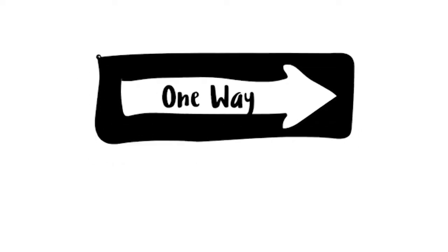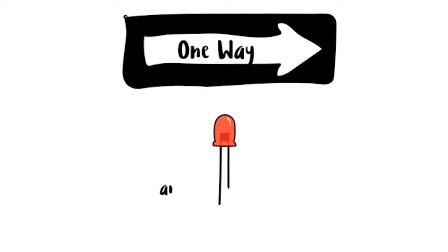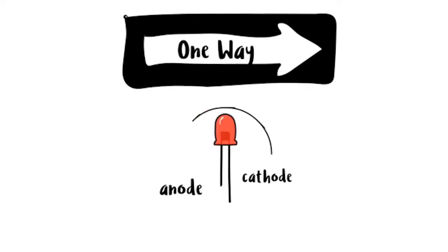A diode is an electrical component that allows current to flow in one direction. In an LED, the longer leg is the anode or positive leg, and the shorter leg is the cathode or negative leg. And the electricity can only flow from anode to cathode. So, if you put your LED in backward in a circuit, it won't light up. The component inside the LED has special properties that allow it to emit light.